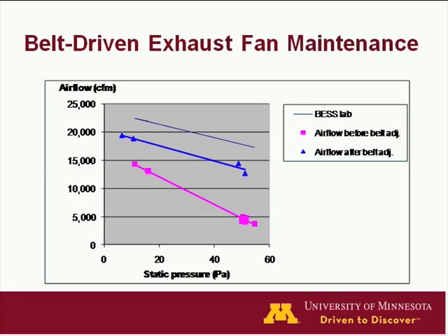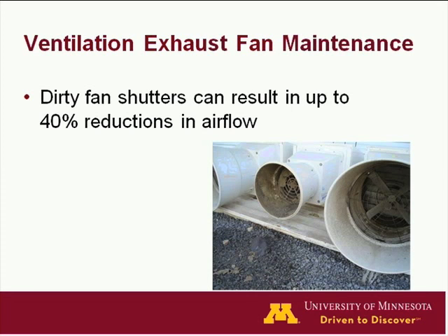After making the belt adjustment, we got the airflow rate up to where the blue points are, the blue line. So we increased the airflow rate considerably by having the belt properly adjusted. So you want to make sure that belts are tight on these large belt-driven fans.